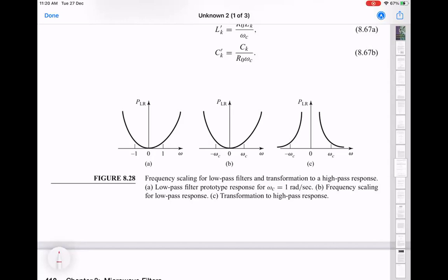but the generic response is always the same, which also means that how fast the filter function falls off is actually related. If you say that it's going to fall off by this much factor over this range of frequency, that range of frequencies you should correctly define as a multiple of the cutoff frequency rather than absolute frequencies.